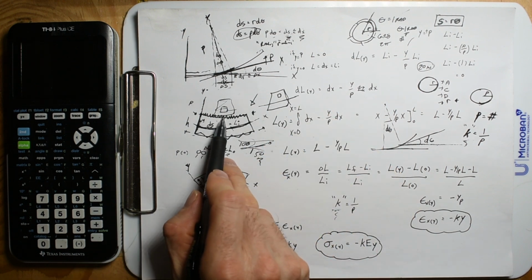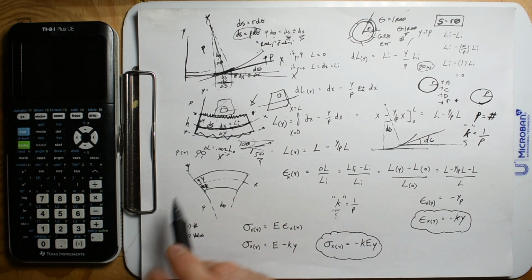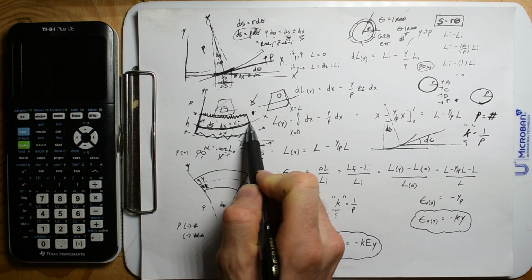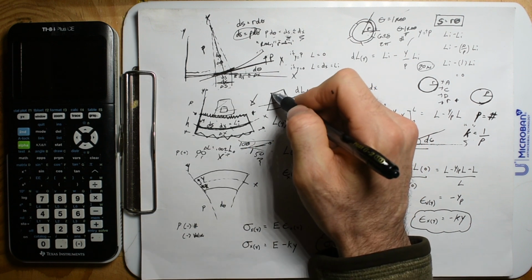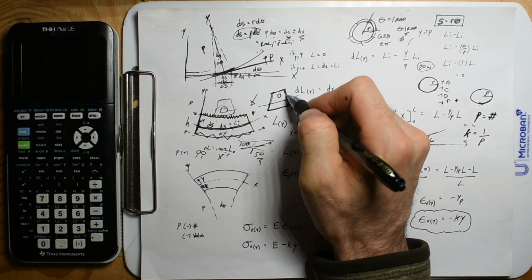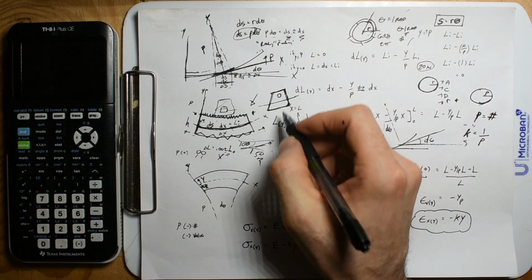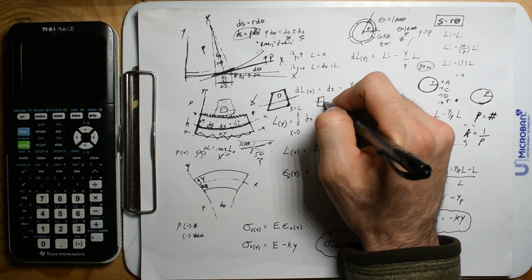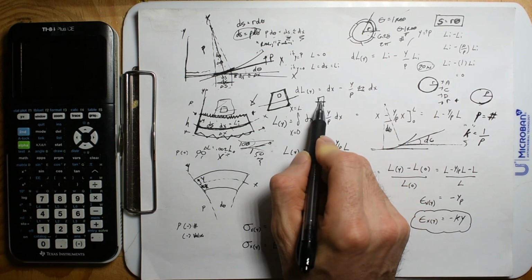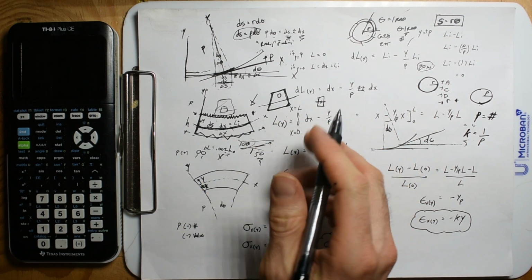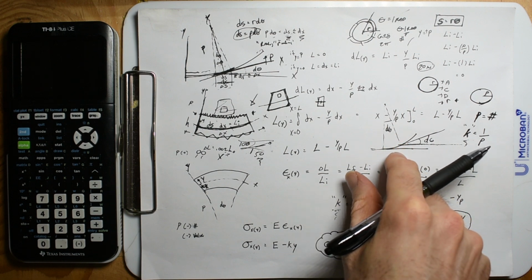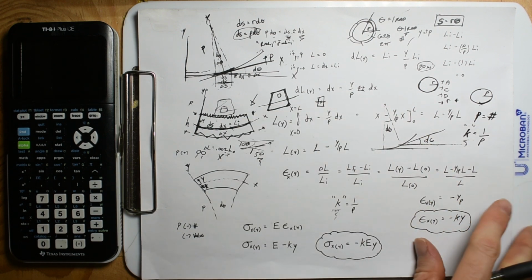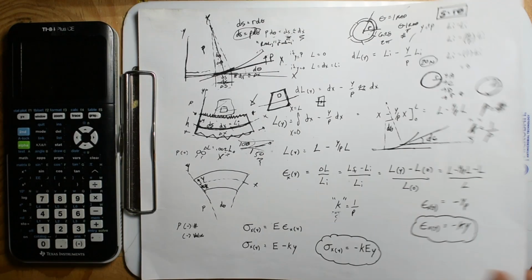Same thing for this compression. It can't be too much. But we're just showing by geometry. If I could figure out where this neutral point is, like for the problem in the book, they use a trapezoid. Because if you did a rectangle beam, the neutral axis is going to be right in the center. So you just keep that in mind. But we don't know that yet. We don't know where this neutral axis is until we start to do the proof on this next page.